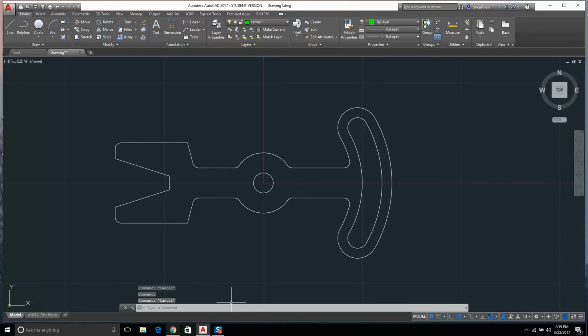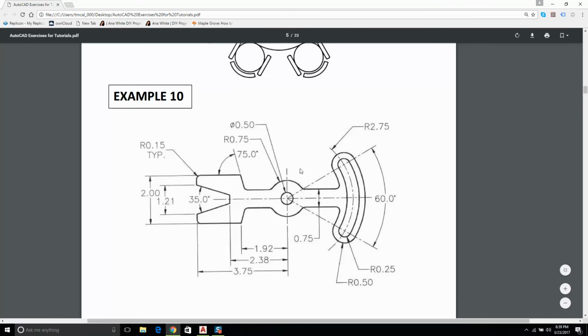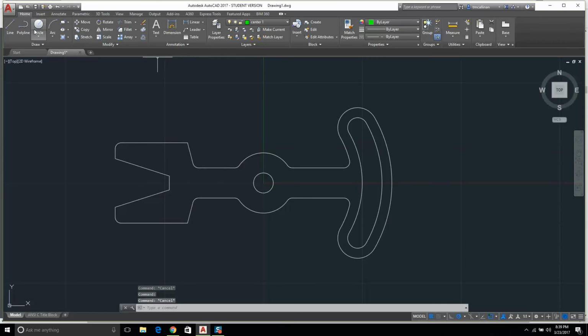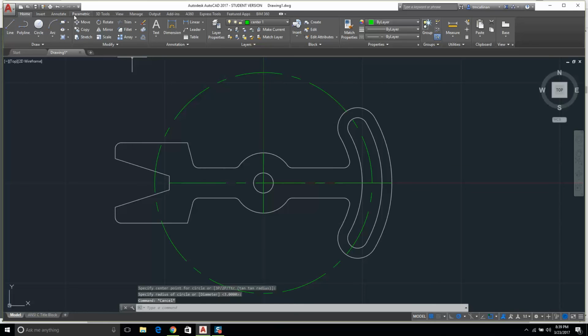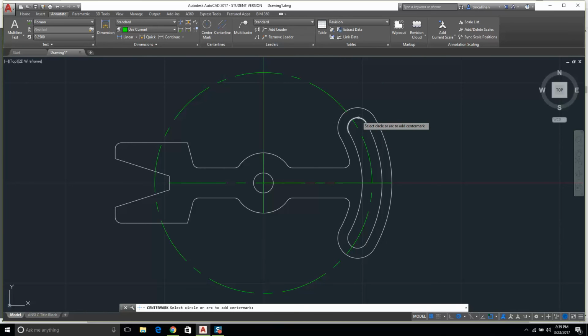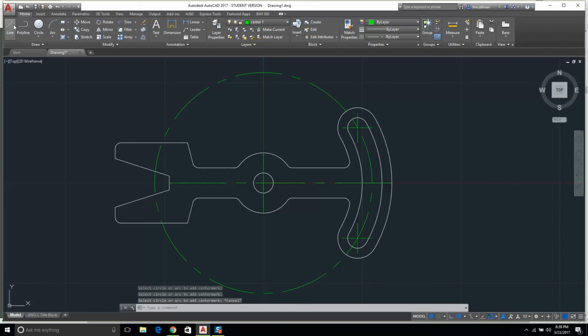Okay. I'm going to put the center line in first. I double clicked on it, and I'm going to put in these center construction lines. So I'm going to start from over here. You'll see what I'm doing now in a sec. I got that. I'm going to get another one from there to there. I'm going to get a circle from here to there. I'm going to click on annotate center mark. Boom, boom. What else do I need? I need those angle lines. So I go from there to there, there to there. I'm going to trim the old construction circle away like it is.